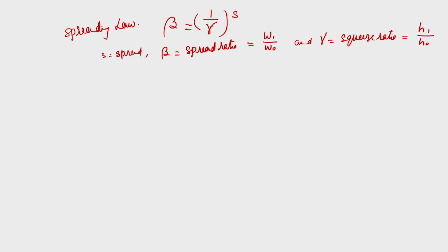But open die forging has certain drawbacks. One is that only a part of the surface under the bite is being deformed at any time. As I mentioned earlier, only a small area of the total length of the piece is compressed; the remaining length is not pressed simultaneously.